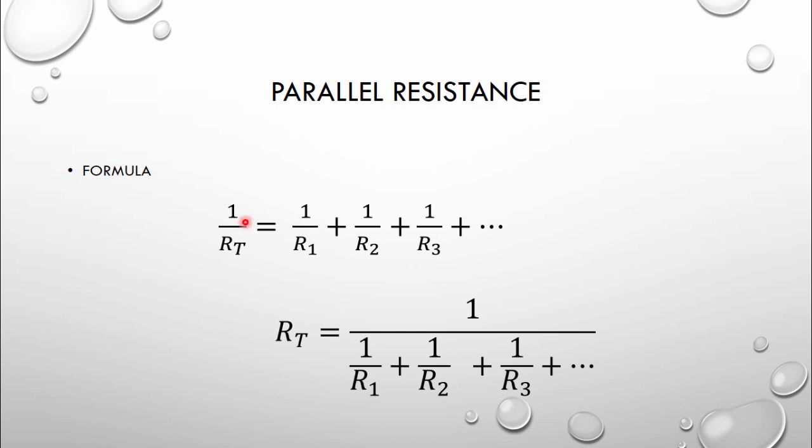But in computing, we can assign 1 over a variable, meaning we need to actually use RT in our C code like this. It means our calculation is for R total, which is equal to 1 over the summation of the inverse of every resistor.